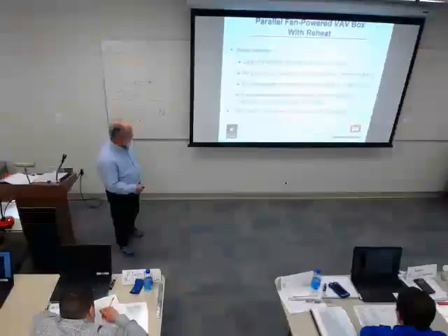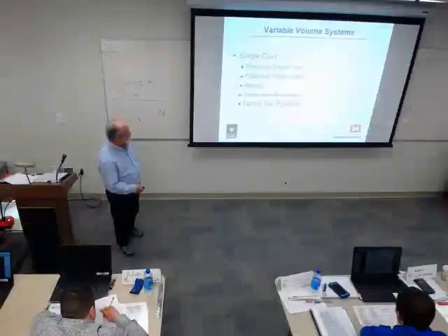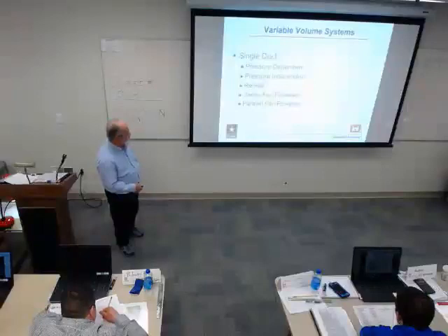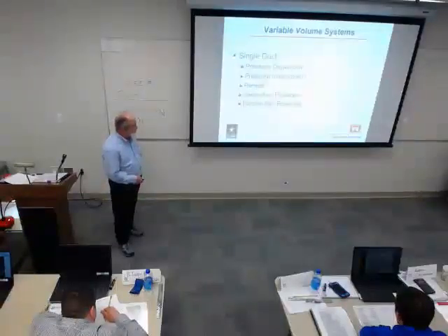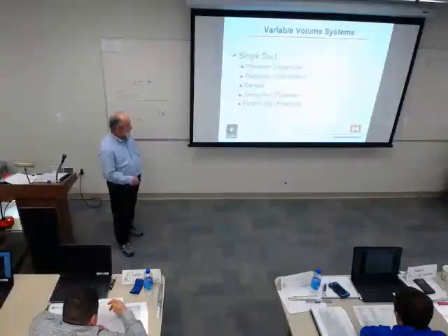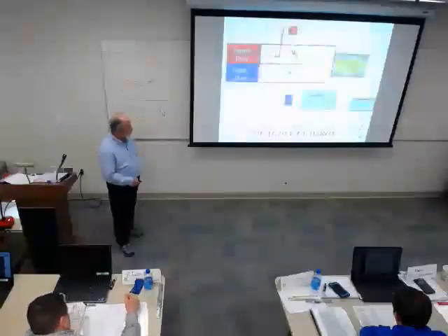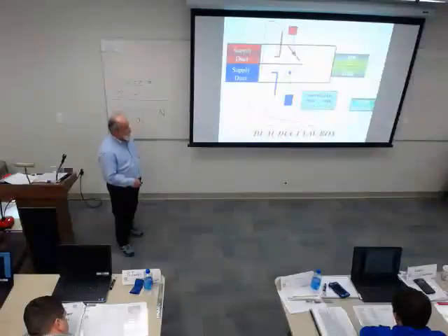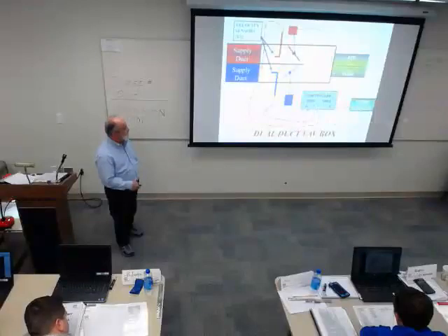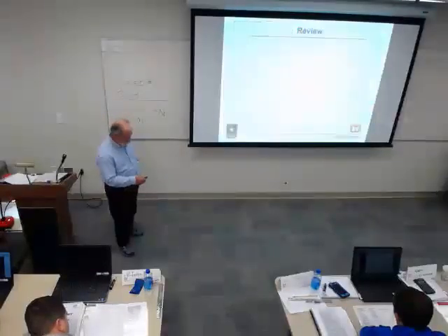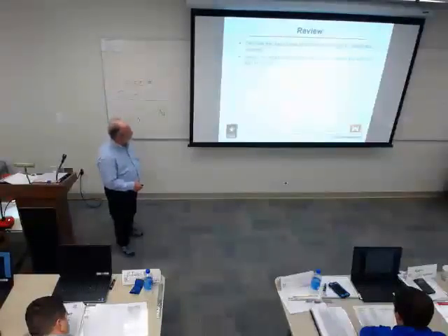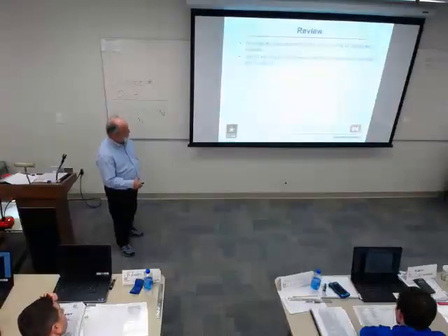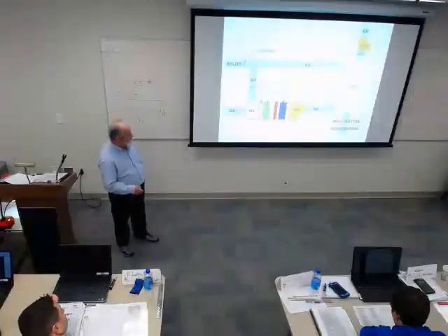Temperature set points, we've already talked about those. Okay, so single duct, we've got pressure dependent, pressure independent, preheat. We have the series fan powered or the parallel fan powered, and those are the variations we have. The dual duct you just hardly ever see. We're just putting it there because you still run into a little bit, and it'll be mostly on existing stuff. Okay, I think we've described those. We've identified the major components. There's our famous picture.